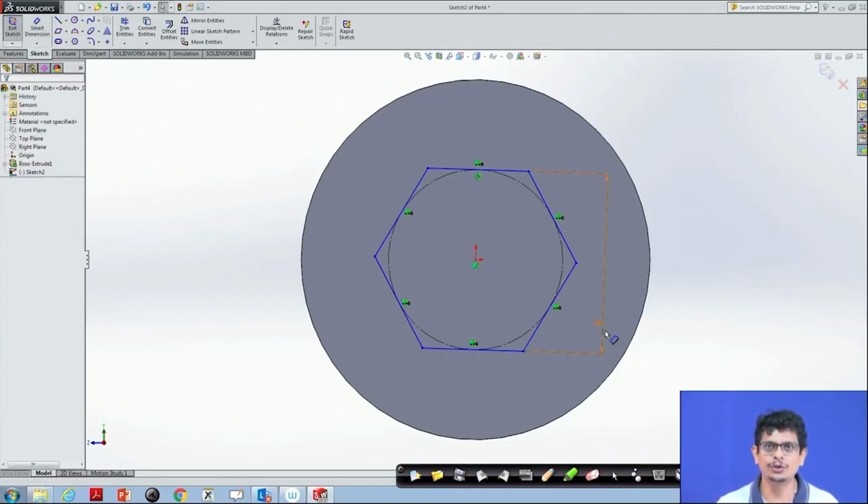Whenever you manufacture or machine a bolt and try to prepare it, there are some standard conventions like the height is supposed to be this much, the length is supposed to be this much and so on, because of design calculations, like you calculate stresses, strains, how much torque you really apply on that bolt, whether it can really sustain it, and what kind of materials one has to use. These kinds of things you will get in machine design data books. So, based on those dimensions, we are constructing this kind of bolt.